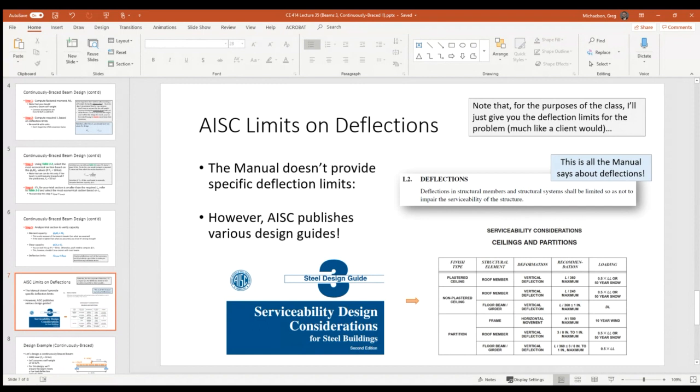They don't experience this stage loading effect like concrete beams do. So I guess I can understand why you wouldn't need to specify it per se as you would in concrete design. I know that a lot of steel designers would like to have codified limits in the code because it's a liability issue. They don't have to say, well, I just guessed a limit. It was there in the manual.